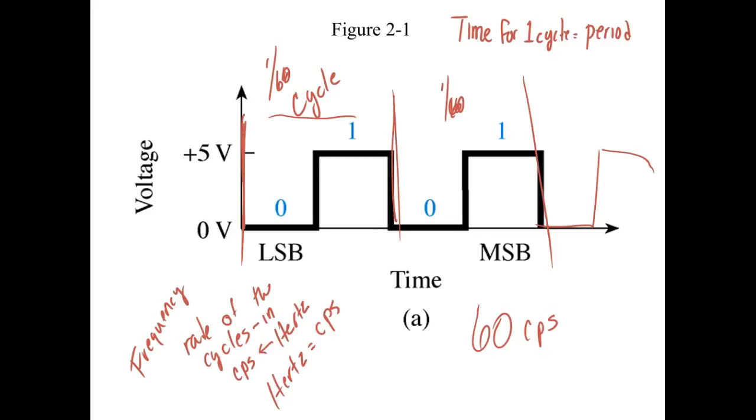So if this was 60 hertz, each cycle would be 1/60th of a second. So the period, which we usually abbreviate with a lowercase t, would be equal to 16.7 milliseconds. And y'all all had intro, so y'all got engineer notation. It's actually 16.66666666. So if you take what we call the reciprocal, which is 1 over the number, you should come up with it.